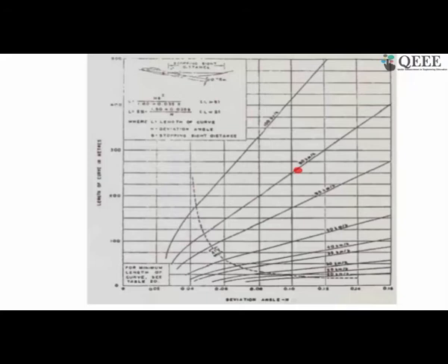On the contrary, if you are at a higher speed than what a valley curve is designed for, when negotiating the bottom point of the valley curve, your car's suspension system can bottom out and hit the bottom of the road. So in either case there is a safety issue, and it depends on how high a speed you are going to go.